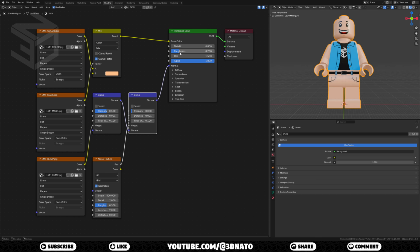And to make it a bit translucent, expand the subsurface tab. Here I'll set the value to 1 and the scale to 2 mm. The first material is complete. We just need to create 2 more. But as all of them share the same maps, we just need to duplicate it and change the base color.